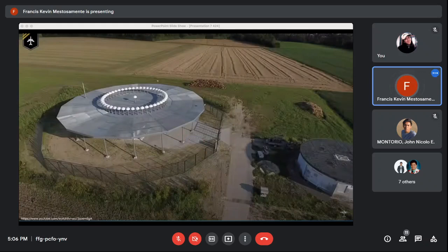So, mamaintain mo. For example, we have a line. Ayan, ganyan. So, kunyari, ito yung sinet out mo. Just for example, so that is the 180. So, using the course deviation indicator ng aircraft, you could maintain yourself going doon sa facility na yon, sa area na yon, or sa airport na yon. So, pag nag-skid ka, malalaman mo yon, skid ka to the right, malalaman mo sa CDI, you could go back on track. So you could maintain on track going to that facility or to that airport.